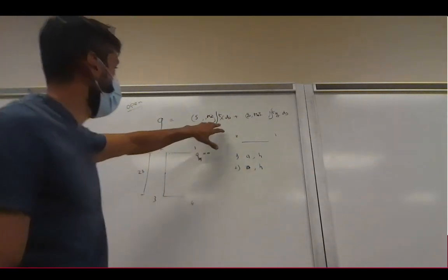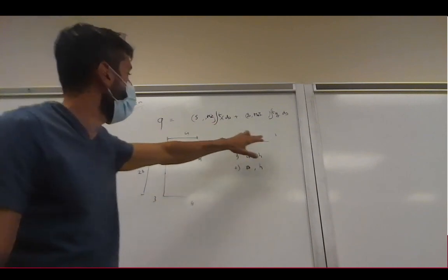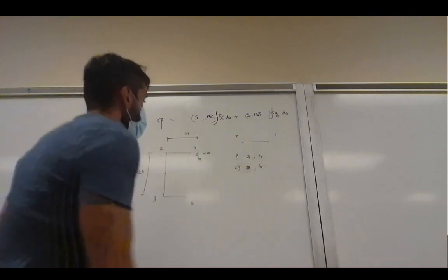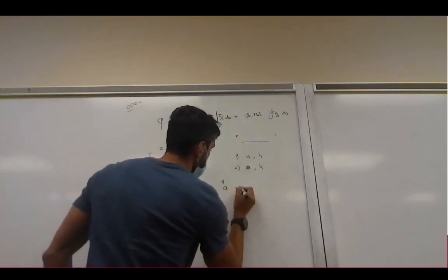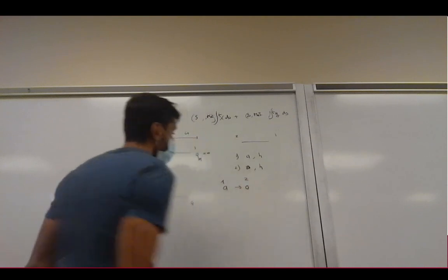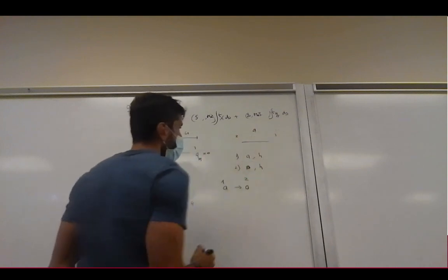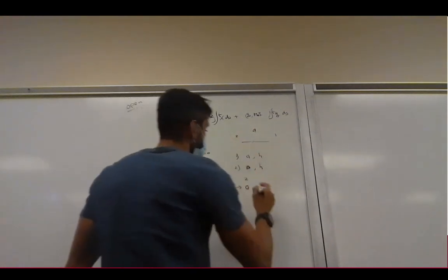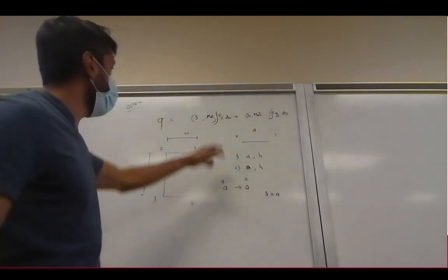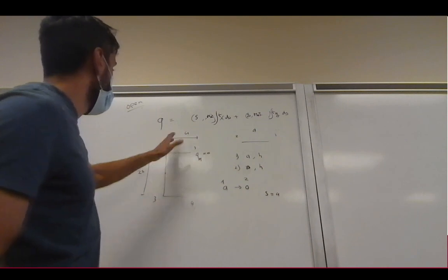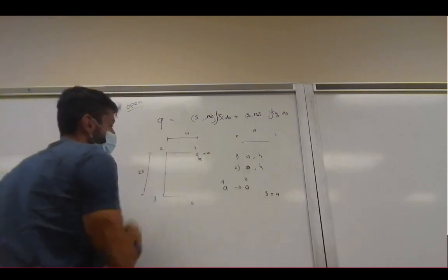So now we have to determine a description of x along this whole segment, along segment 1 and 2. So we know that a goes from point 1 to point 2, and goes from a to 0. And we know that the length we travel, the path traveled, is equal to a. So the path s traveled is a. So now we have to come up with an equation that is valid at any location along this segment.